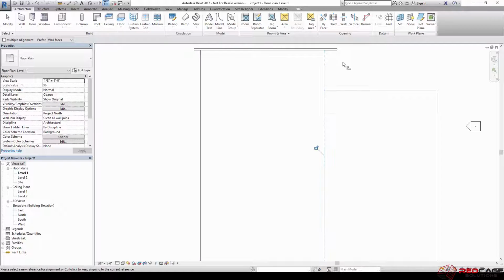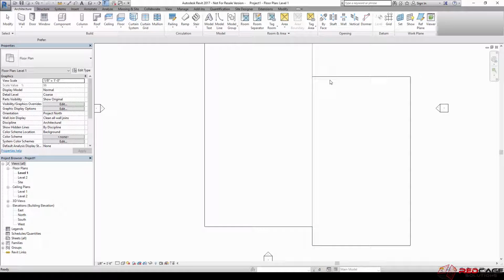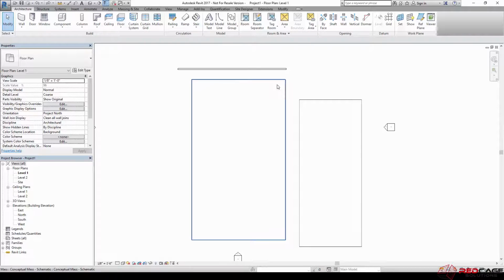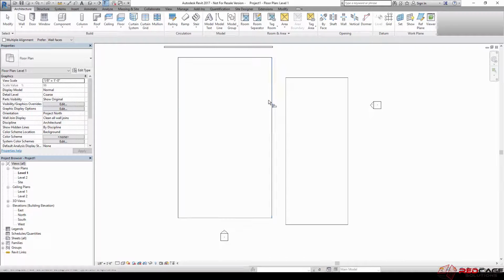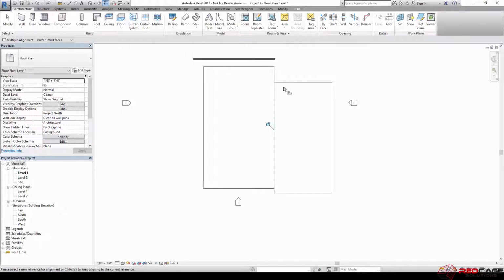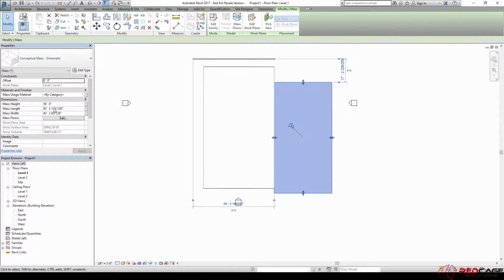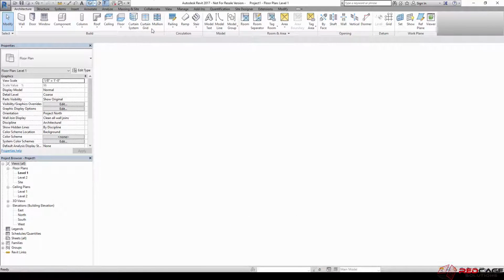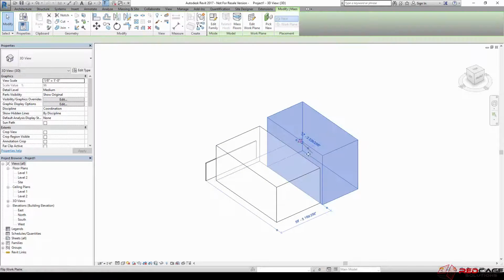If you missed that, this time when I hit align and I change where this line is, watch what happens with this line. I grab my reference, select this one. This one stays the same, and now essentially my instance parameters have changed to suit my modify tool. If I hit align and move that over, you'll see some different behaviors using these different reference types.